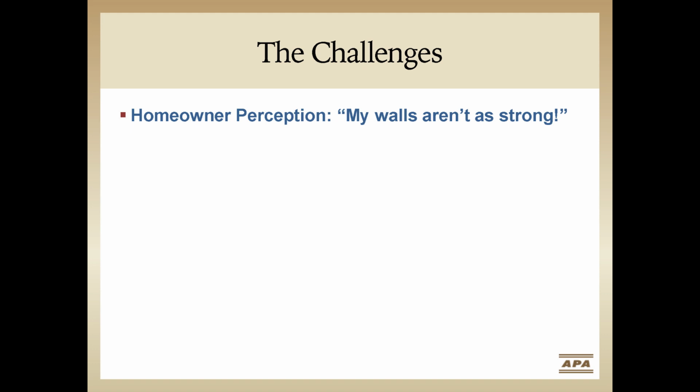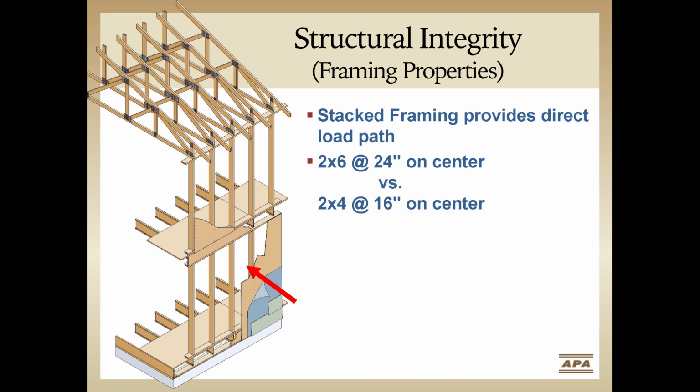We've looked at the structural integrity of 2x6 advanced framing, so let's take a look at what we've found. Let's review the differences between a 2x6 wall spaced 24 inches on center and a 2x4 wall spaced 16 inches on center. This comparison involves looking at loads in 3 directions as well as both the studs and the wall sheathing. So I'm going to start with a comparison of the studs, starting with loads normal to the wall. And normal loading is indicated by the red arrow.